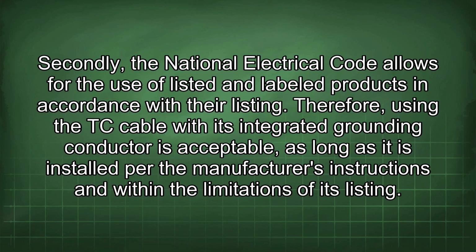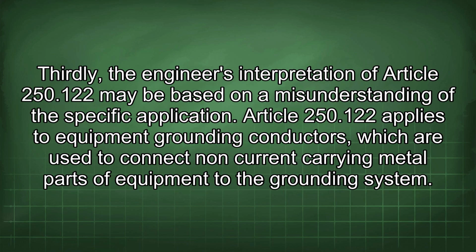Therefore, using the TC cable with its integrated grounding conductor is acceptable, as long as it is installed per the manufacturer's instructions and within the limitations of its listing. Thirdly, the engineer's interpretation of Article 250.122 may be based on a misunderstanding of the specific application.